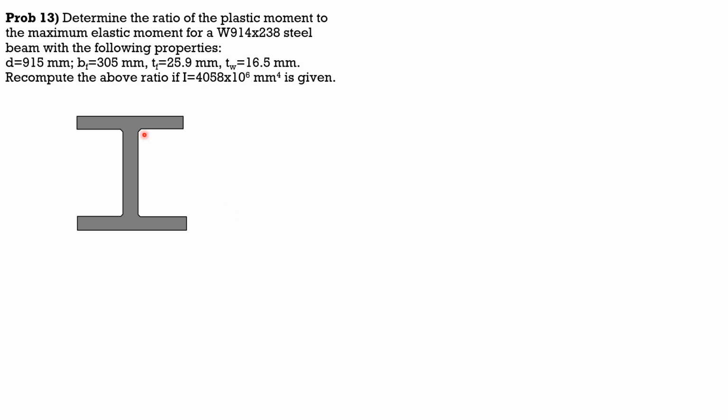So first, let's treat the parts as component rectangles. So it will give us a lesser value because of this fillet here, which fillets are not accounted for in this actual moment of inertia with respect to the x-axis. So we expect that the moment of inertia by treating this as rectangles will be lesser than that. But if not even, we always treat this as rectangles to compute for the moment of inertia.